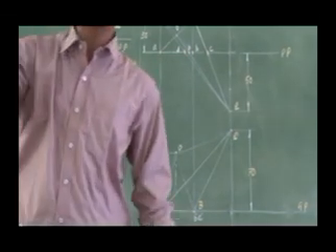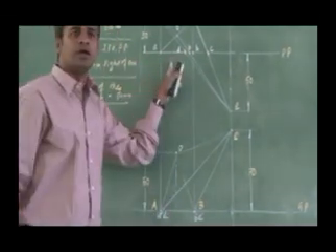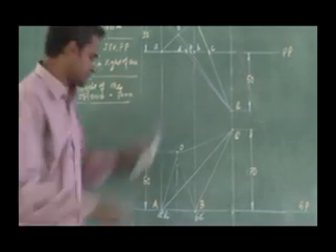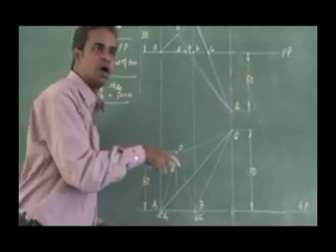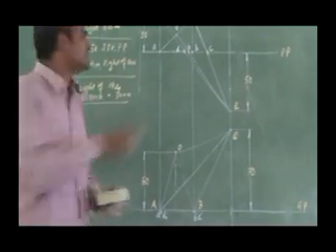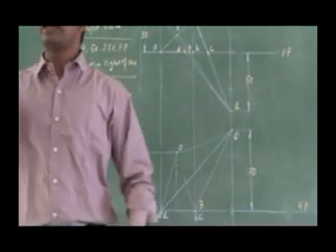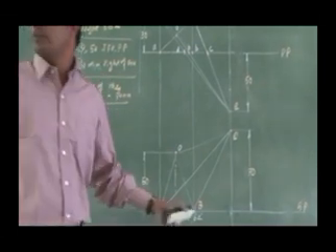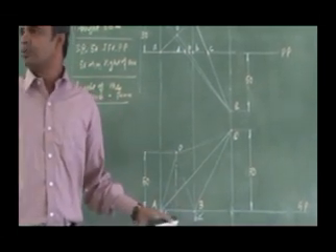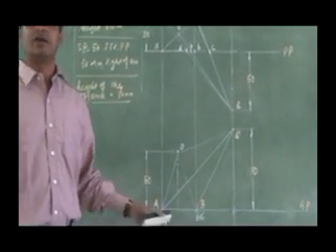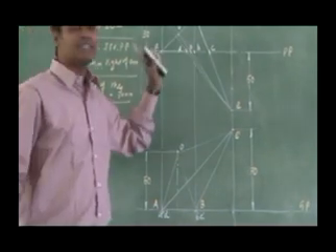So the same size of 30 mm in my object appears in my perspective also, because this edge AB is touching the picture plane. The same size I will obtain in my perspective also. Right? So the size will be the same if the object is touching the picture plane.